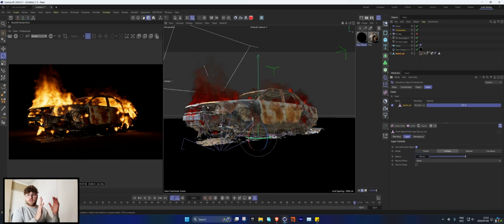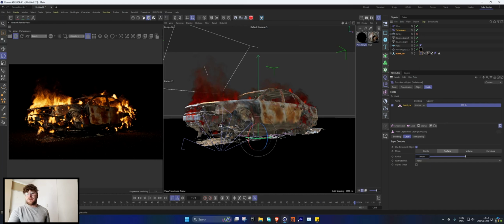The reason for this is because the flames are actually pushing the smoke. And then once the flames aren't pushing the smoke anymore, the smoke's just kind of moving upwards, compared to the way that we have it now, where it's just turbulence that's being applied to the entire scene. We want to apply it to just that part. In Houdini, you can go and only apply turbulence to just the temperature. So that means that it's only the temperature that's getting disturbed, which will disturb the density, but as the density moves up, it's not getting disturbed anymore by the flames. That's the cheat workaround that I did to get to this type of look. You don't have to do it, you can just leave it without, but I feel it sometimes works.